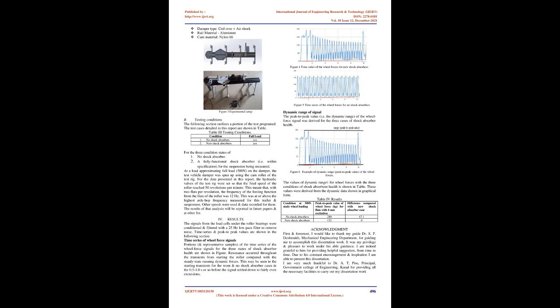Equation 8, where F is the unsprung mass excitation frequency. Equation 3 implies that the acceleration will depend on the sprung mass in addition to the excitation frequency. Simulation has been performed with the quarter car model to evaluate the effect of change in the sprung mass on comfort. Input parameters used in the simulations are given in Table 2.